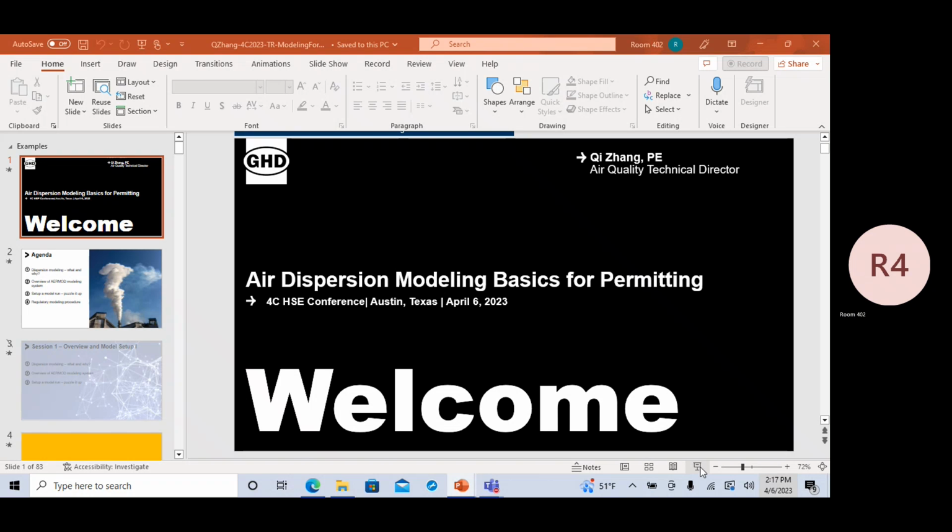Better not. Because remember the raw data being processed in AERMET is also paired with different surface characteristics that you get from the AERSURFACE run. The AERSURFACE run will tell you surface roughness, albedo, and Bowen ratio. These will be different from county to county. So if you have the data, don't just use a neighboring county. Okay, so what if my model results are not favorable with TCEQ's data, but I believe TCEQ's processed data is not representative of my project site?